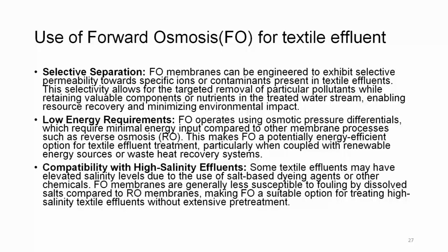Low energy requirement. FO operates using osmotic pressure differential, which requires minimal energy input compared to other membrane processes such as RO, reverse osmosis. This makes FO a potentially energy efficient option for textile effluent treatment, particularly when coupled with renewable energy sources or waste heat recovery system.